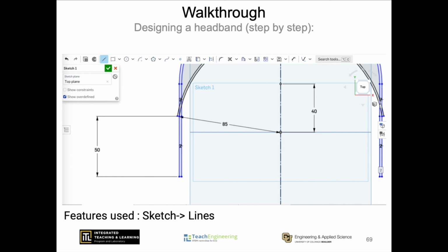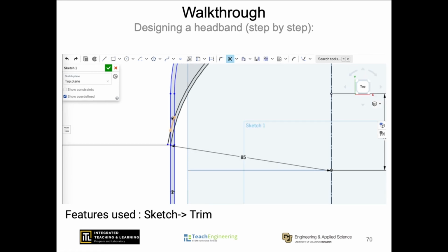Delete the construction lines on the two sides. Select the upper arc, Offset, arrow pointing downwards, and then offset a distance of 2 millimeters again. Trim the extra sections on both sides using the Trim feature. Make sure that the area between the lines is gray, indicating the figure has no holes and is closed completely. This will be useful in the Extrude feature.